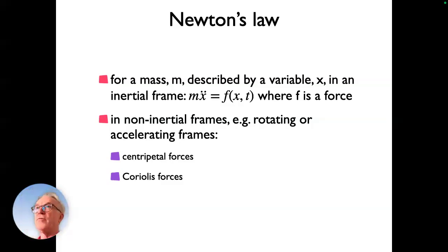So the non-inertial frames have these other forces. Now you will see in robot arms that occurs always, because if we're looking at one joint, it is attached to the kinematic chain, and that joint will very often not be in an inertial frame. Now, because I'm moving around my shoulder, my wrist is actually now in a frame where the velocity vector changes direction, right? And that's non-inertial. It's an acceleration due to rotation, and that creates these forces we originally called centripetal forces, sometimes also called centrifugal forces. It's just a question of which way around you look at it. And Coriolis forces.